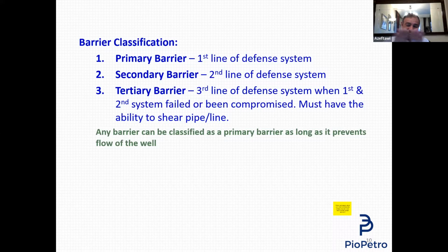When you close your secondary barrier, which is the BOP, if it closes and seals around, then if you ask me, what is this, Ahmed, I will say this is our primary barrier. So the BOP, which is originally a secondary barrier, became a primary barrier now. And it keeps acting as a primary barrier till you fix your primary barrier, which is the stuffing box or the stripper, and it's back to work. Now you open your BOP, and it goes back as a secondary barrier.